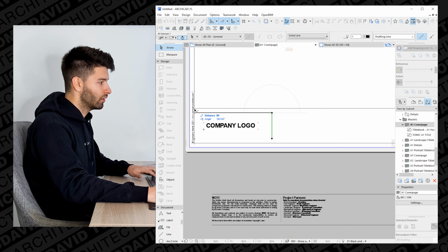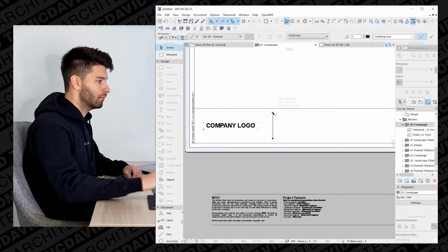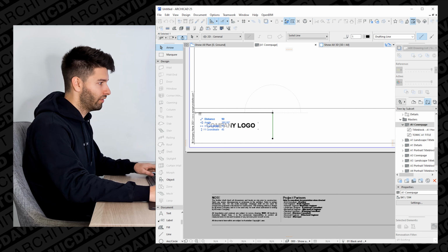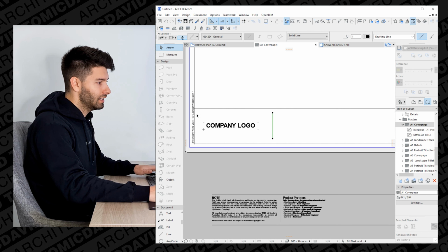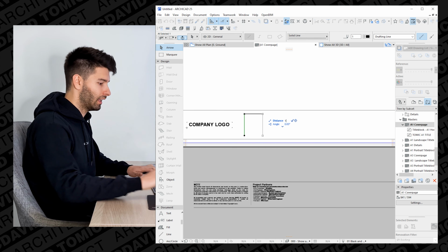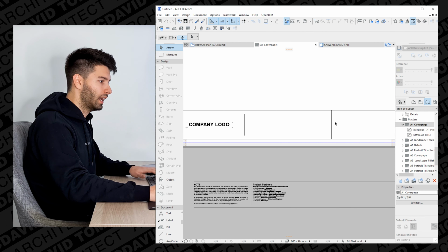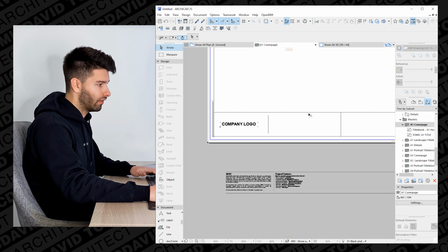So now we're going to make sure this line is offset perfectly from here. So let's go 90 minus, which means it's perfectly 90mm away from that line. And next, we're simply going to drag that line 120mm across and drag it all the way top to bottom to finish off that box.